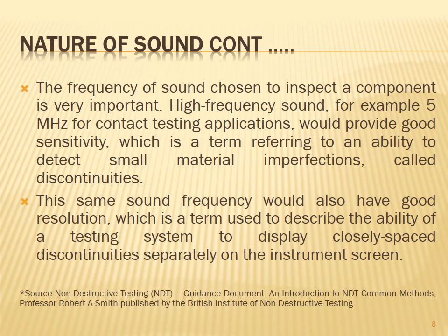This same sound frequency would also have good resolution, which is a term used to describe the ability of a testing system to display closely spaced discontinuities separately on the instrument screen. Some components, such as castings, can have a very large grain structure and, as a consequence, are difficult, if not impossible, to test with high frequency.